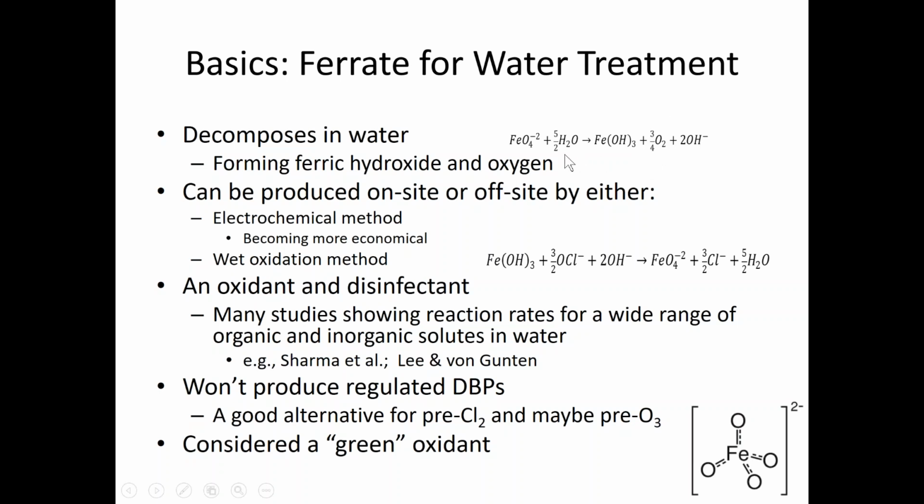And so what it essentially does is it precipitates as ferric hydroxide solids and oxidizes a little bit of the water to oxygen, but oxygen's great. There's no downside to this. So this is one of the reasons why we refer to Ferrate as a green oxidant.